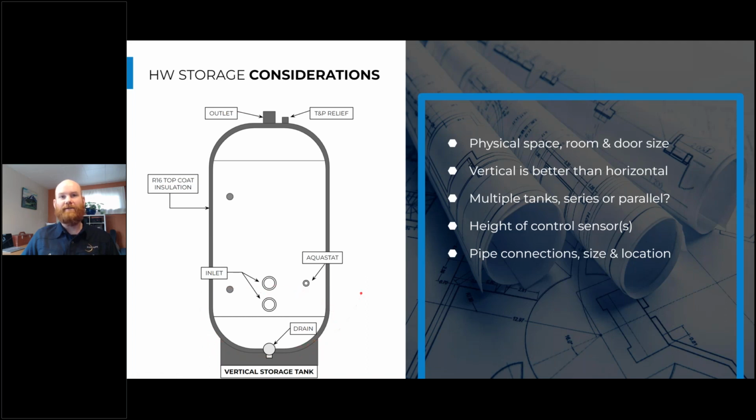So we're going to reduce the effective volume of our storage tank. So pulling our inlet as far down as possible is the best you can get. Typically, it's not at the very bottom of the tank, but I believe tank manufacturers are looking to design a tank that way specifically for heat pump water heaters. But understanding where those connections are and how they relate back to our multi-pass or single pass heat pump water heaters is one of the key considerations for success.